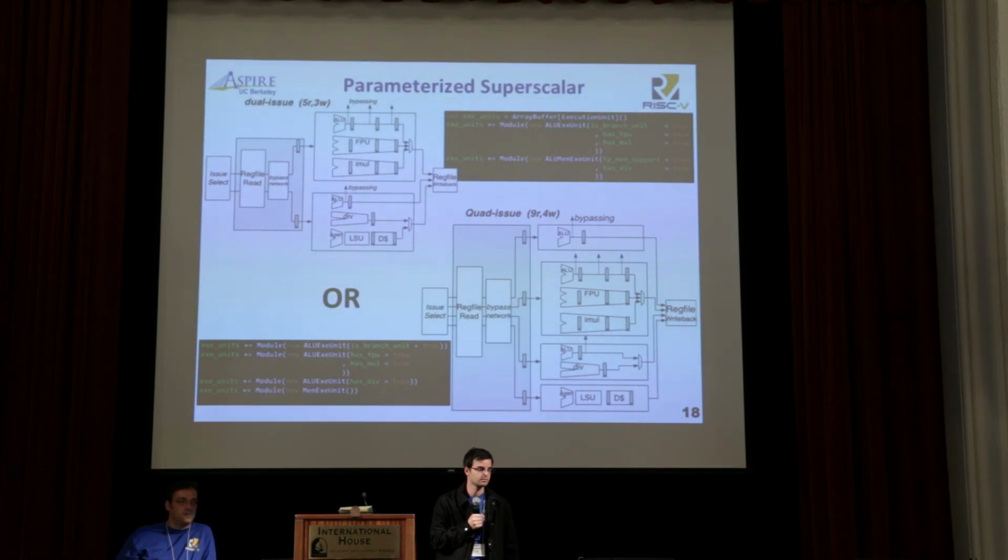You said the simulator is fast enough, then, is it a cycle accurate simulator? So all my results are done using the RTL. Chisel can generate ASIC Verilog, FPGA Verilog, or a one-to-one exact copy of the RTL running in C++. It's just like running an RTL simulation, except we had a few tricks to make Chisel C++ run really fast. So that's a model that's exactly cycle accurate. You can poke any individual wire or register and see the value of it.